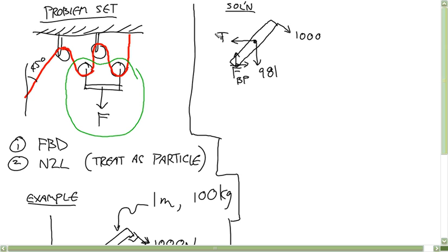Using the rotational second law, if you chose your middle point and did everything about it, you lose the weight. That's right. You lose the weight and the tension force in your moment equation. That's totally correct. I chose it here, and then in our moments we lose that F_BP. So you gain something and lose something in either case.